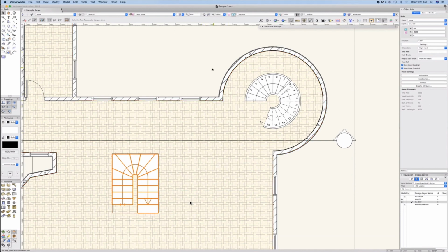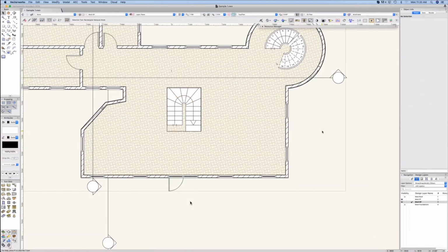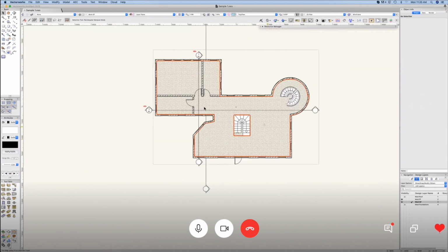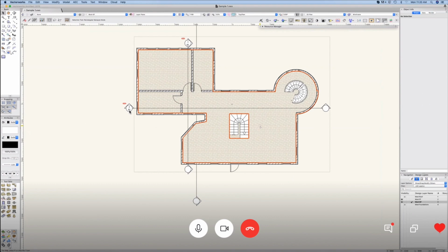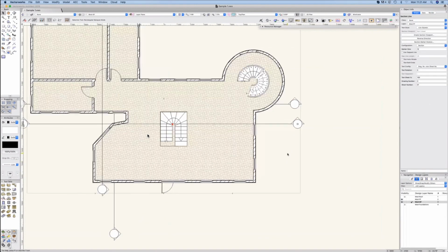So I think you know enough about stairs to practice now. And what would be nice now is, let me show you something. If you go back to your section drawings, let's move the section so it cuts right through one of the stairs. Take Section 3, move it down. And how about if you rotate it, Command L, rotate it left so it's cutting through the length of the stair.